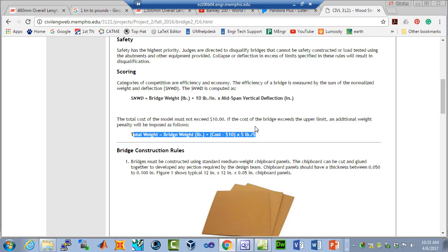Also, don't forget that around the center line of the structure, what do we have? We've got the 240-pound load, and it's distributed over 6 inches. So over the middle 6 inches of the structure, I have a distributed load that totals 240 pounds. So what is going to be the intensity of that load if 240 pounds is distributed over 6 inches? Yeah, it's going to be 40 pounds per inch. So that's the load that we can put into our analysis.